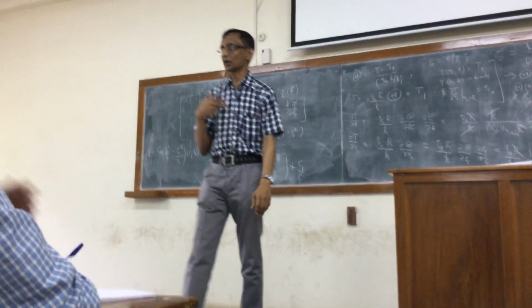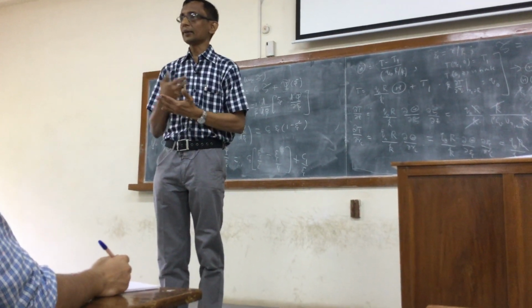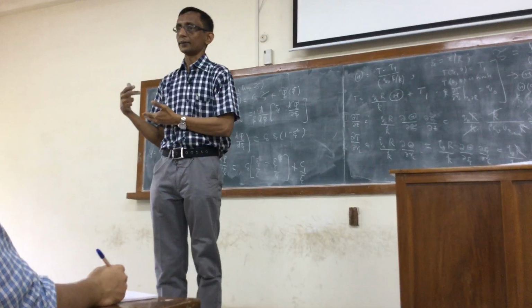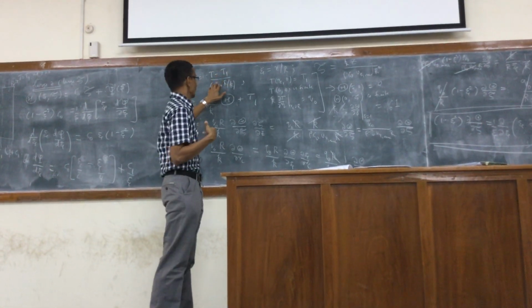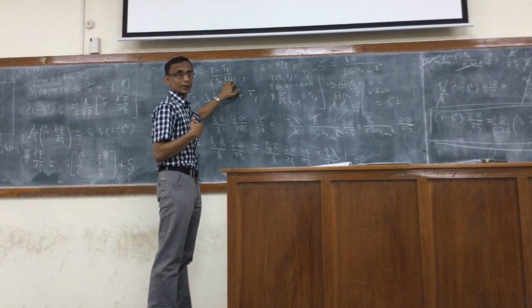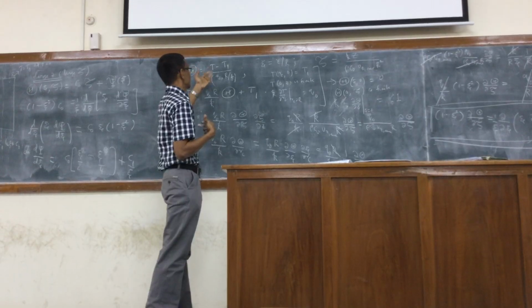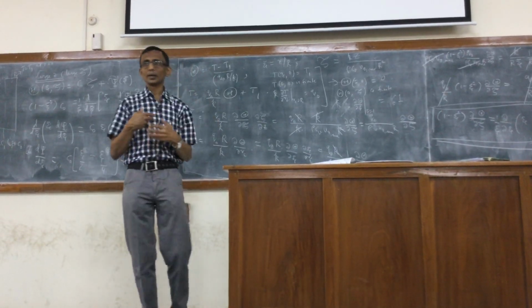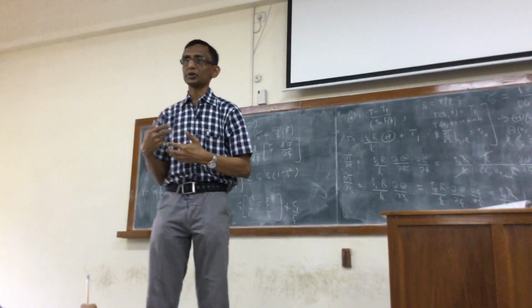There is difficulty if you write it at the outset, because r_c there is a characteristic length radius, but z as well as T there are others. Why is this q naught by k coming? No need for it, simply T minus T1, but T divided by T1 or something. But it is coming to simplify the problem in terms of the dimensionless variable.